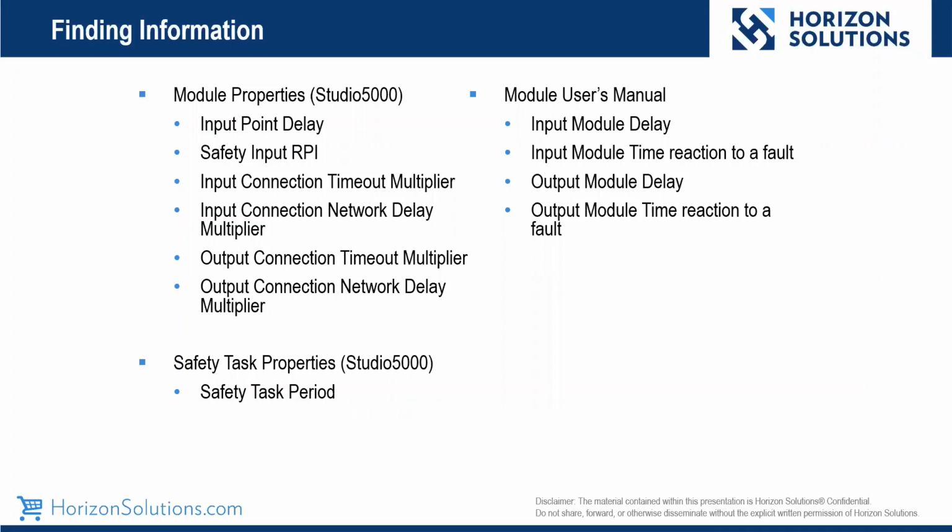Moving on to the safety task properties, this is where we would find the safety task period. The safety task period is simply a count of how long it takes maximum for the outputs to be updated within a safety task.